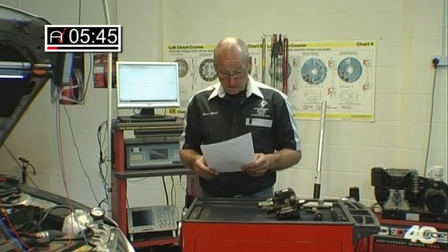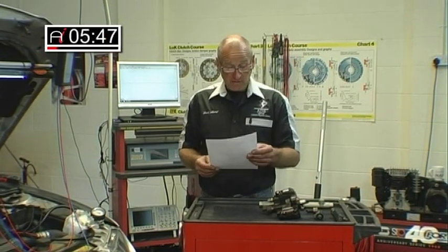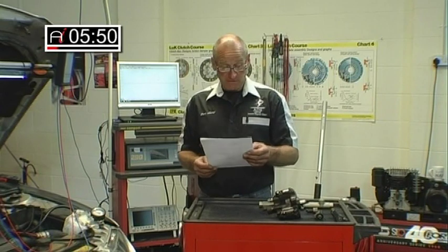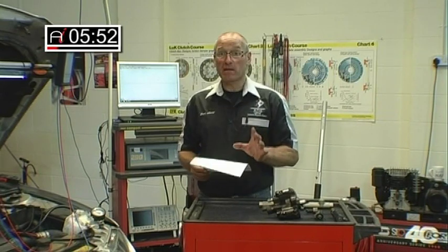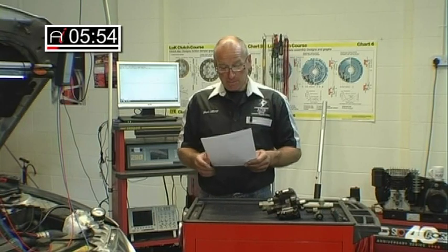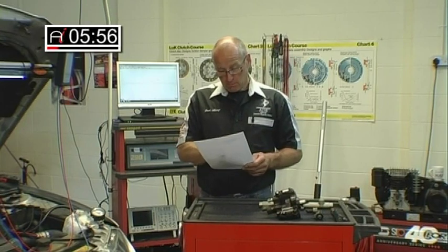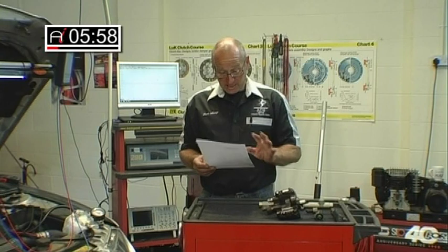It will not give me a no start condition. We have a P1E45 status intermittent. All of these, by the way, are intermittent. Capacitor 1 voltage, booster voltage too low. Now what that